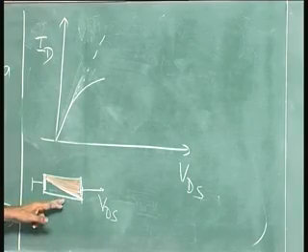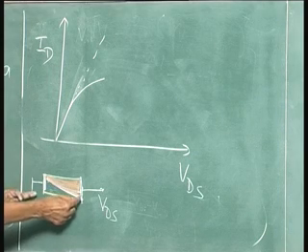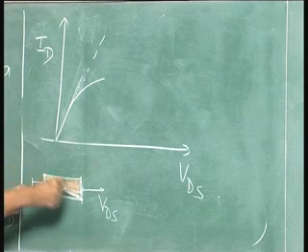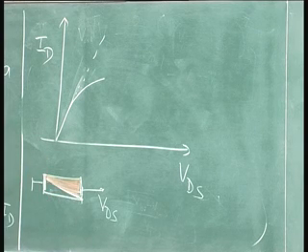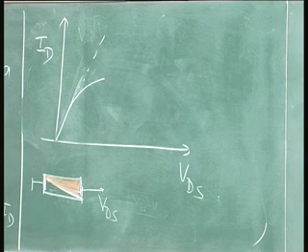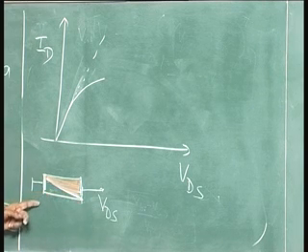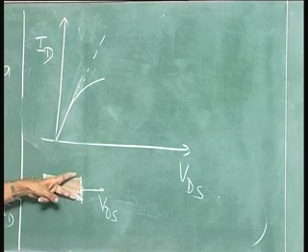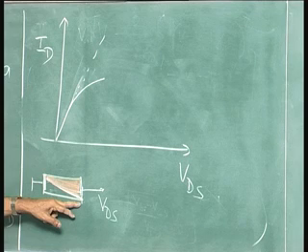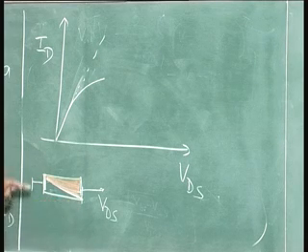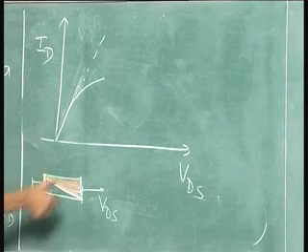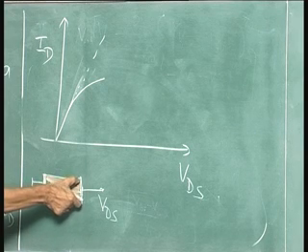At that point, once this happens, the resistance shape is like this, and there is a voltage drop here. What is the voltage drop there? The voltage drop there is such that the depletion layer width is almost close to that. The depletion layer width should be such that it is almost closing, but there is still a small opening. Let us say that is a delta. So, there is a small opening here, and the depletion layer width you can say is almost equal to A.